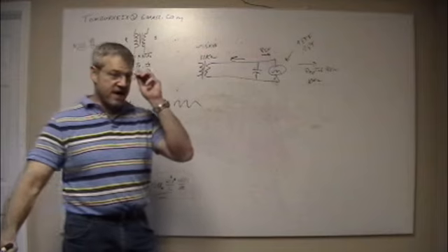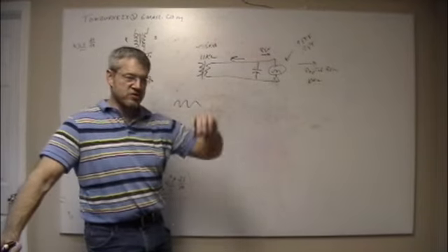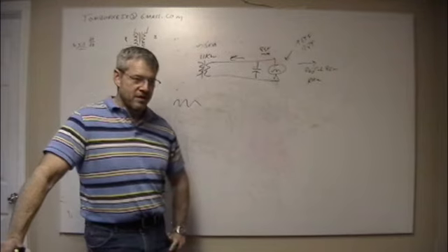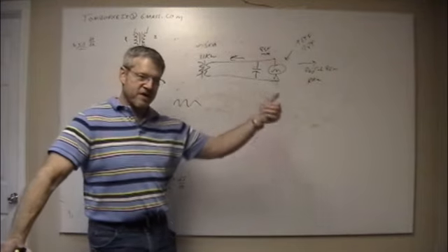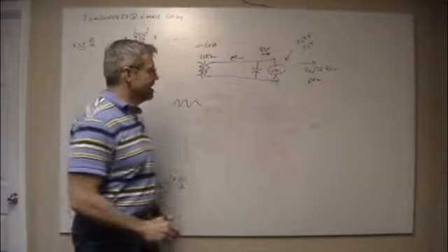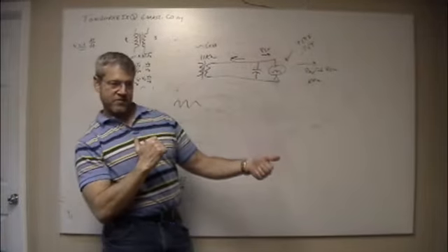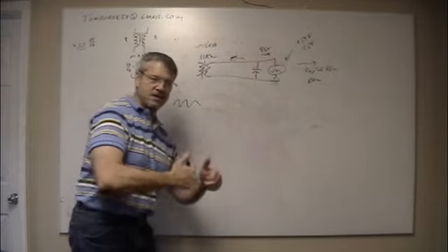So what you'll see at some factories is they will set up a whole bunch of motors just running, but because they're running with no load, it causes them to pull the power factor forward. And these other motors that are actually doing the load are trying to pull the power factor the other way. And it balances out.